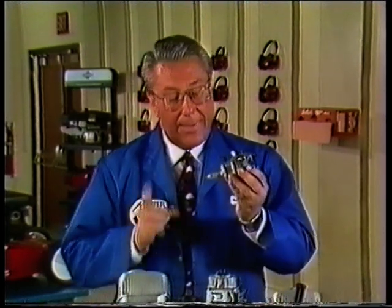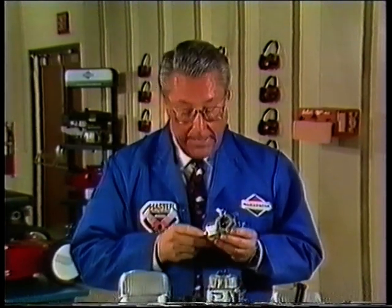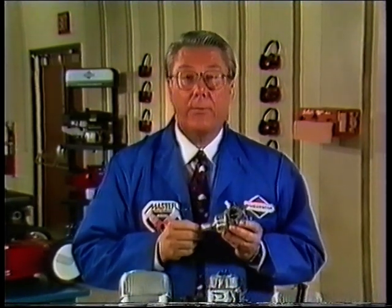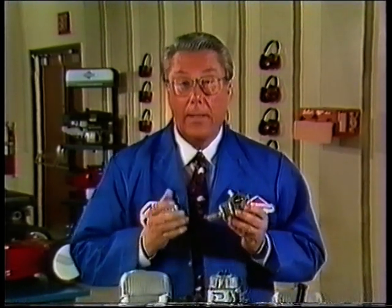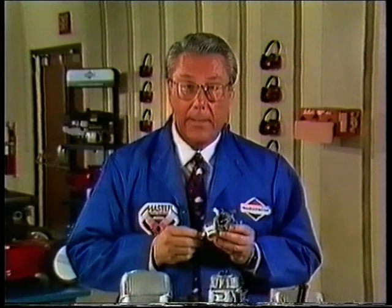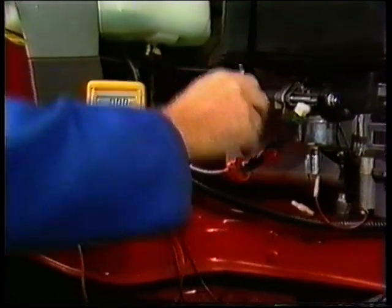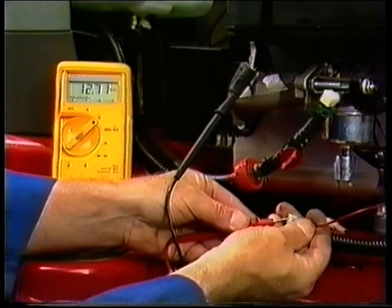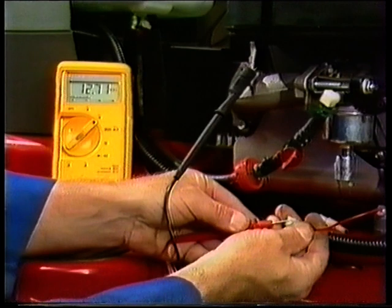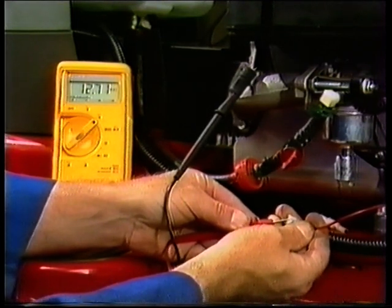Sometimes carburetors with anti-afterfire solenoids experience starting problems. This can happen if the solenoid is not receiving electric current, or it can also happen when dirty gas is used, or gas has been stored a long time and has gone stale. Test the anti-afterfire solenoid system by checking for battery voltage at the spade connector with the key switch in the on or run position. A positive result indicates the problem lies somewhere else.